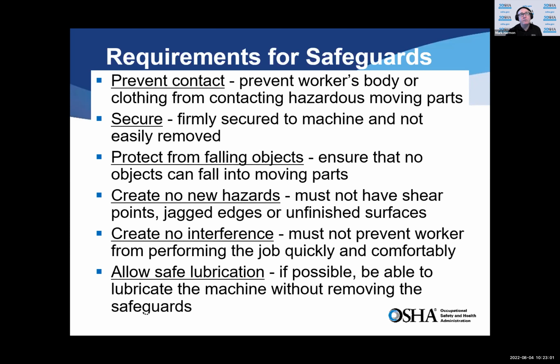Expanded metal, if you've ever seen that type of web material made of metal, is very good for machine guarding because you would be able to see through it, perhaps. Sometimes we see that they don't protect the edges, and it becomes a laceration hazard where you could cut yourself by just grabbing and touching it.